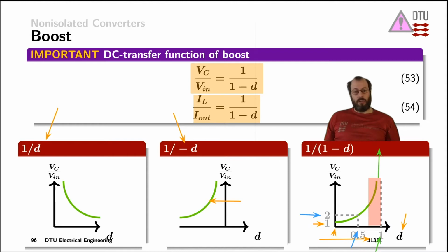First of all, with the rising output voltage, we get a rising output current, and that means we also get voltage drops across the series resistance of the inductor in the circuit, as well as voltage drops during the conducting diode. So that would limit the amount of output voltage that we actually could get out of a boost converter. And that limit practically looks around like that in this graph.